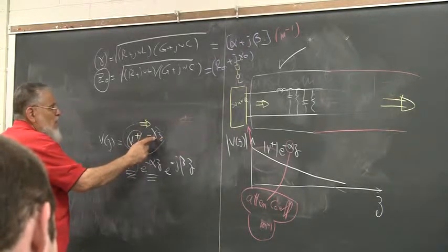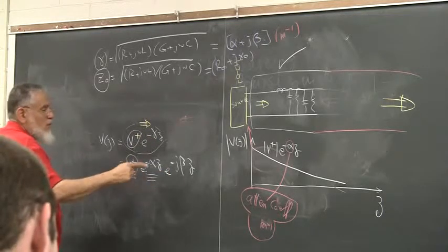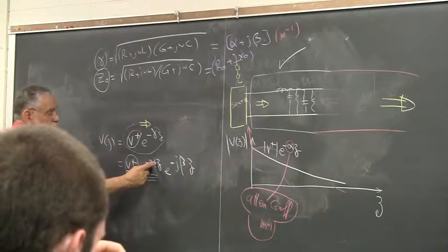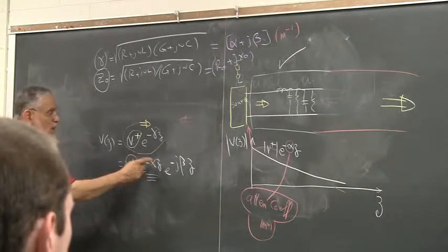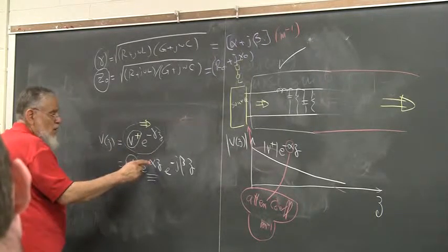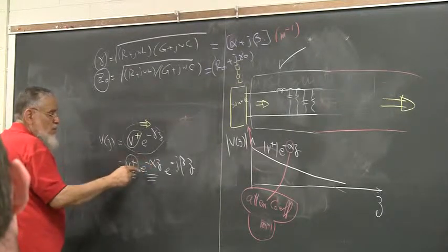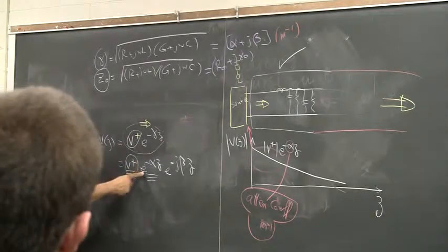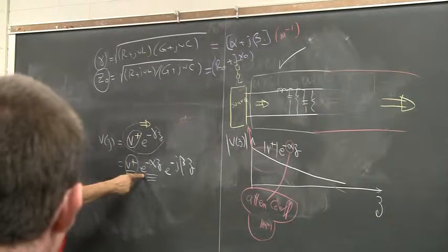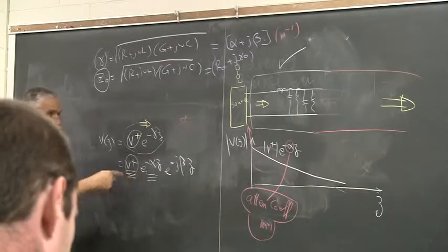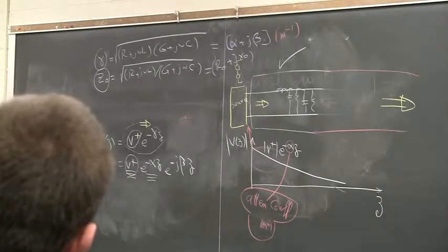So this one here, the alpha, is now the decibels per meter, or the Nepers per meter. If the exponent here is e, then we use the Nepers. If the base is 10, it is decibels. The decibel is a more common unit in the commercial world than the Neper.